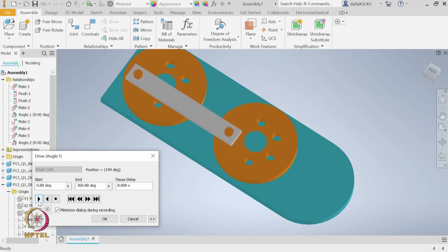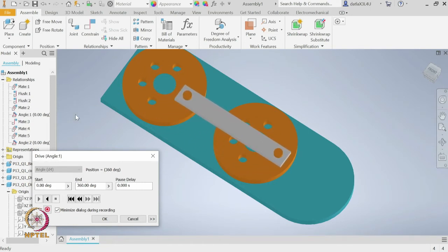We see that we have only specified the rotation for the first wheel, but since we have defined the constraints, this first disc is now driving the second disc. With this problem we are able to give a degree of freedom to one of the components and see how the other components respond. There is another way of specifying this using a parametric equation.